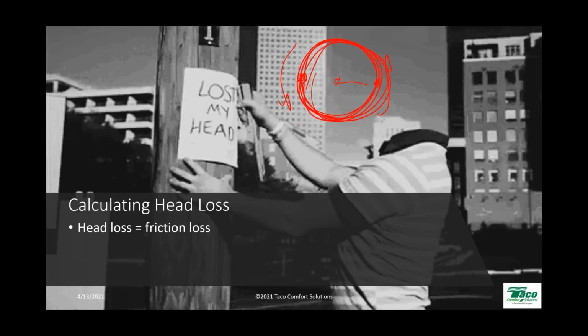So when you're talking about friction loss, all we care about is the length of the run, okay? And the length of the run is from the outlet side of the circulator all the way around back to the inlet side of the circulator. Now, new construction, maybe, or you can measure it and figure it out. If you're doing a boiler replacement or something like that, the best you can do is estimate, all right? So you measure that length as best you can, and then to allow for valves and fittings and stuff, you simply multiply by 1.5. We're adding 50% to that length to allow for valves and fittings and stuff that's in the way.